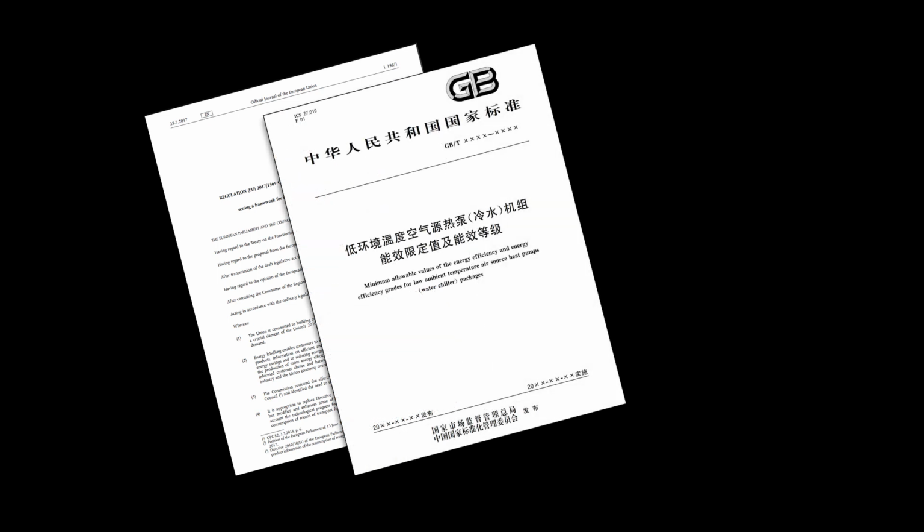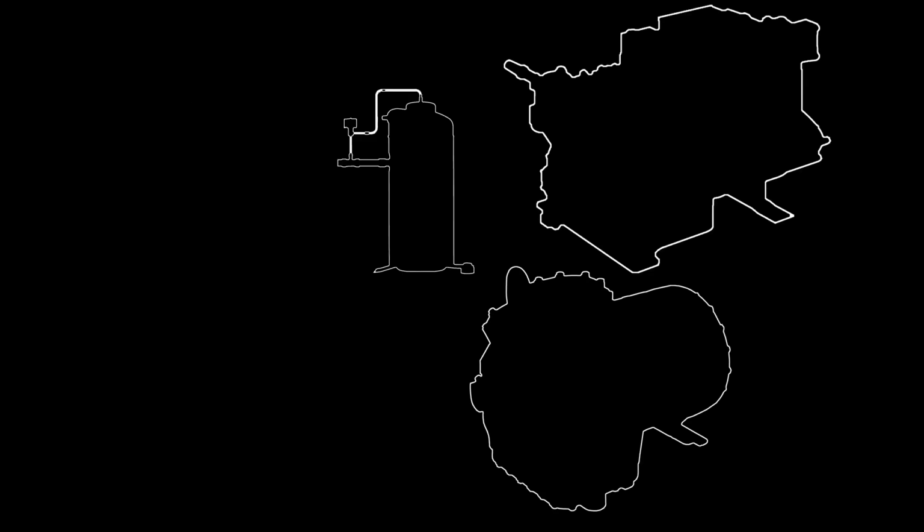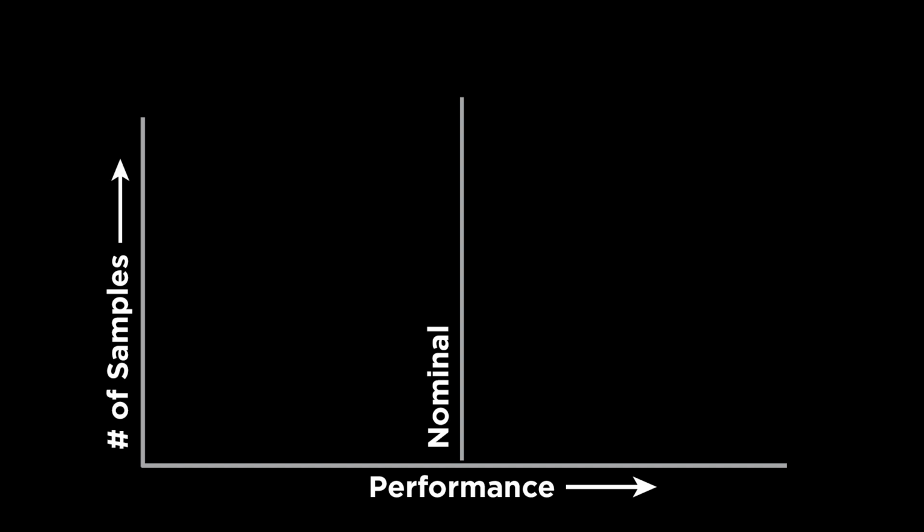As regulations on operating efficiencies of air conditioning and refrigeration systems drive towards minimum efficiency performance standards, attention is shifting to the uncertainty in performance of the various components that make up these systems. With compressors, published ratings denote the mean performance, as indicated by the nominal performance line in the center of this chart. But the variation from the nominal performance can be traced to 5 primary sources.